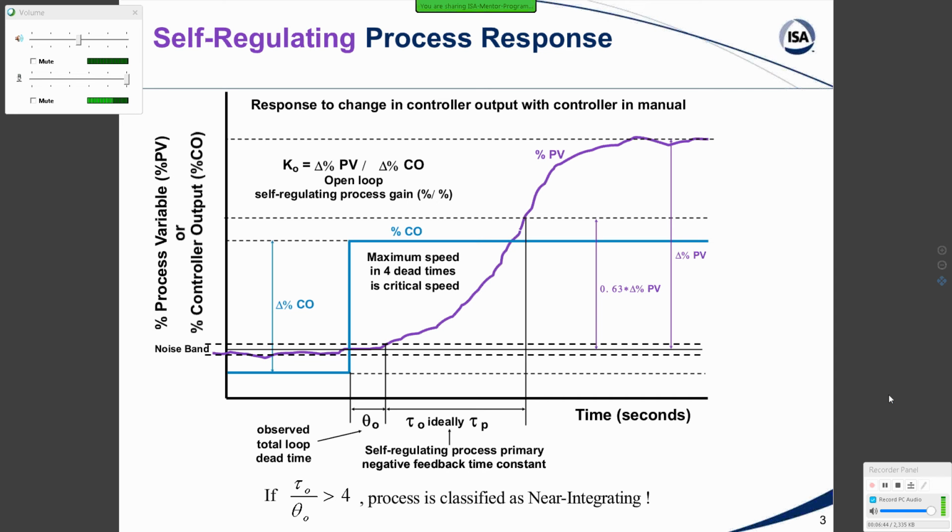I expect it would help internal model control and Skogestad's internal model control tuning as well, although I haven't kept up with either one of those internal model control tuning settings and actually all the modifications that have sometimes been proposed, to know if anybody is advocating this. We just know we need to advocate it when we use lambda tuning.